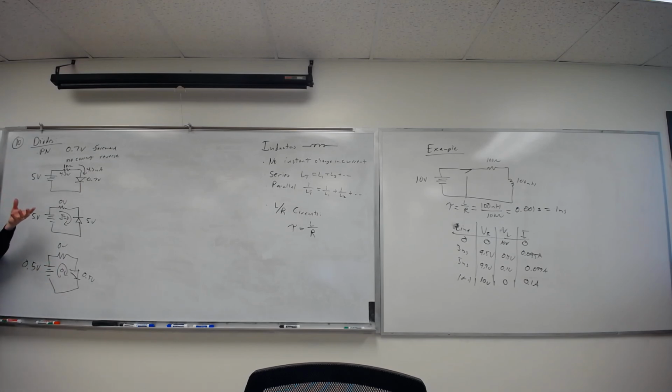Yes, germanium, I'll give you the voltage. It could be 0.2 volts. Also, if it's an LED instead of a p-n junction diode, I'll give you a voltage. So beware, I have done that before. Oh, it's a red LED. It has 2 volts on it. And then half the class goes 0.7. I'm like, it says on the schematic and in the problem too. So, yeah, read my problems, because LEDs have a different forward voltage.